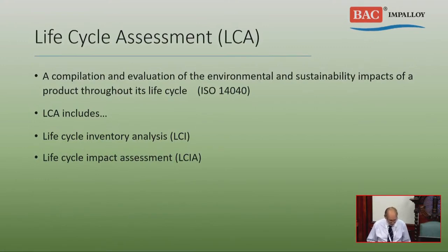And the amount of current you need has direct sustainability impacts. The amount of current that you need is basically the product of the wetted surface area and another factor called the current density, which is the amount of current in amps per unit area.